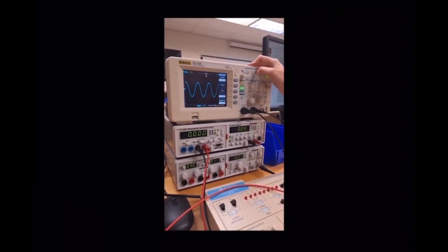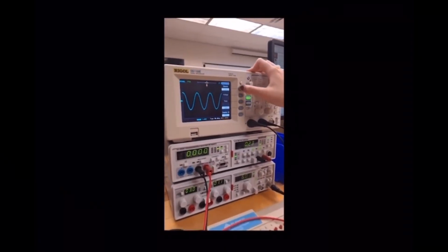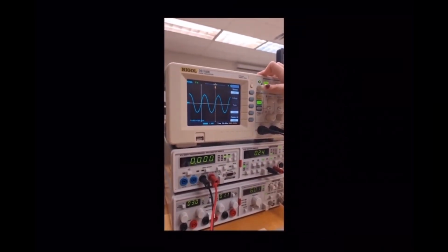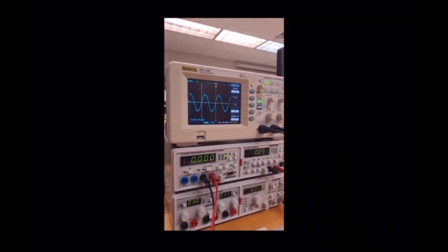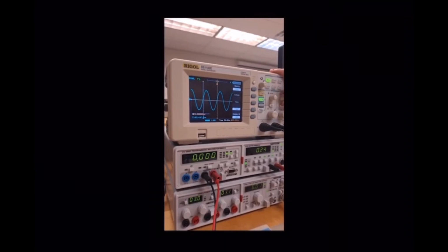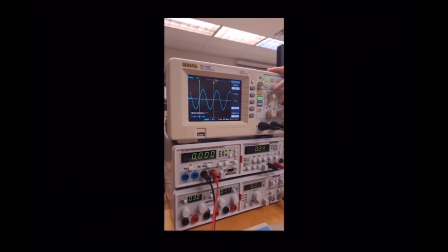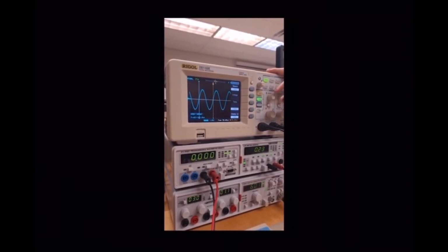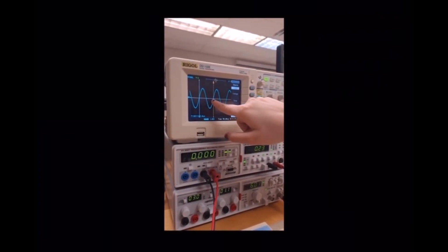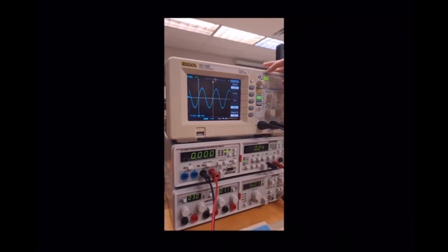Now for our period, we can measure it 2 ways. First, with the new school method, you'll hit measure for channel 2, select time and then period, and it shows 168, maybe 167 microseconds. The other method would be our old school method of counting squares. So adjust the scale as needed to make it easier to see your divisions in comparison with your sine wave, and just count the squares along the horizontal axis since we are looking at time.